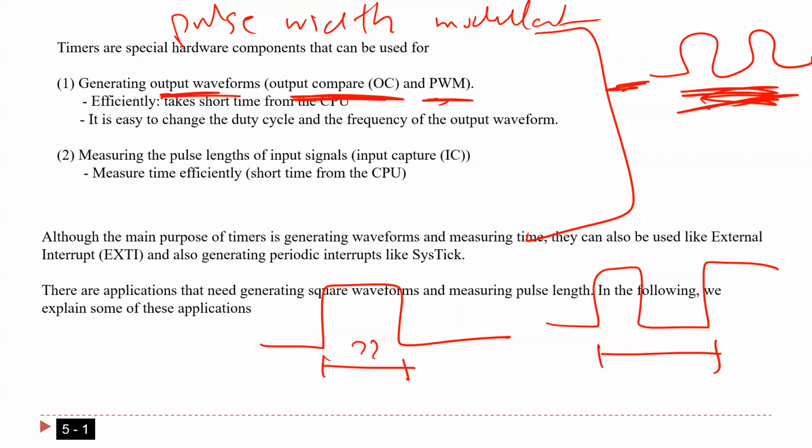Okay, guys. So conclusion: in what application can we say, yes, we need the timer? Okay, you need the timer if you want to generate a square wave, efficiently change the duty cycle efficiently. Also, if you want to measure time. So I'm going to give you for sure more details. So this is the main